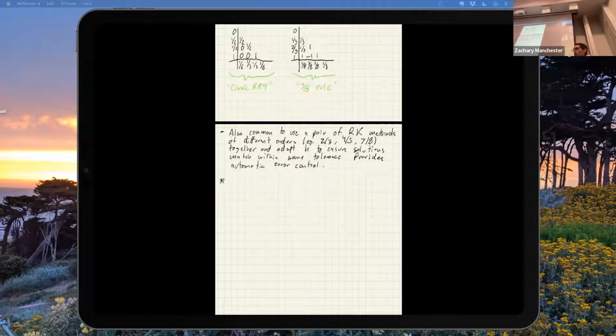What can happen is that on a particularly gnarly ODE, something like ODE45, you may have seen this if you've done a lot of this, it'll end up having to take tiny time steps and basically bog down and take forever to simulate something. We can make it do this trivially, like the pendulum example. If I do that, it'll have to take multiple kilohertz time steps and do really poorly.